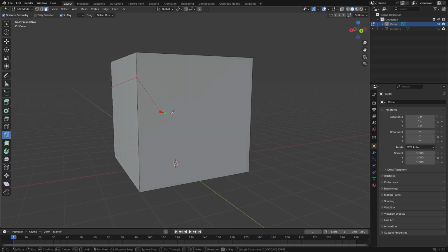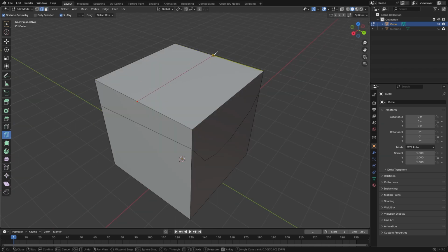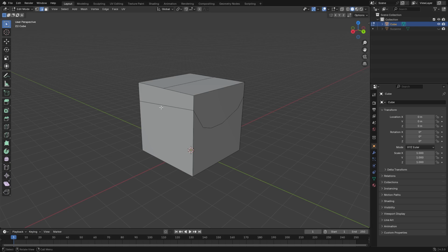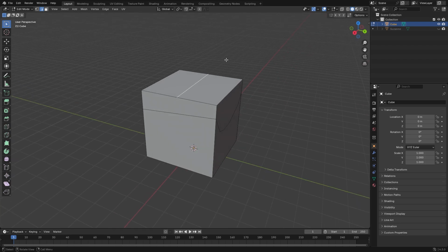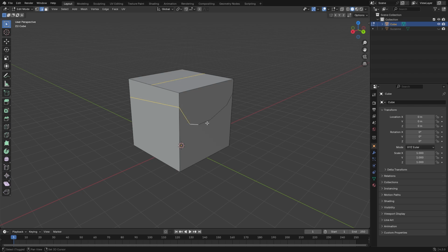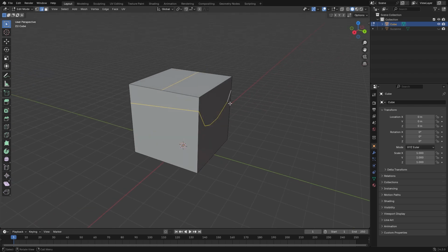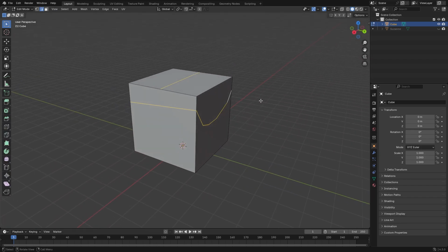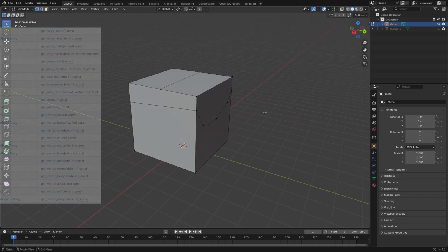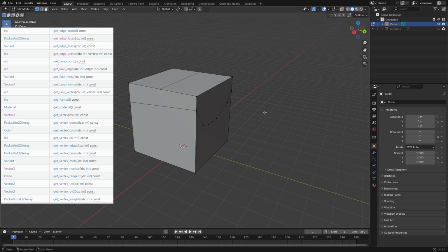So what I want for customization is to be able to just knife here something like this. And then we mark this concrete edge as a grabbable edge. We mark this as, I don't know, a rope or some rail. And this we can mark as a thin beam to enable that balancing slow walk. Then we do some operation and export the thing as a GLB. This way these edges are in phase. That means that they will be put into the static marked data pool, but then they will be deleted during the data triangulation phase and won't have any effect on the collision complexity for this shape. But Mesh Data Tool just can't really do that for us.